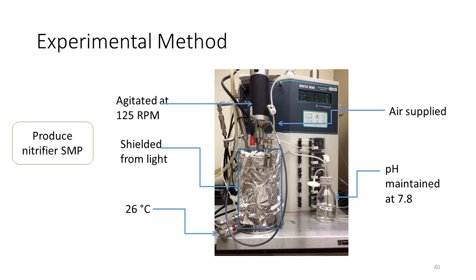And this was key because during ammonia oxidation, the pH goes down. However, the nitrifiers would die if the pH dropped below 6. So as the pH would continue to go down, the machine would continue to add carbonate. It actually served two purposes: it supplied them with more carbon source and it would raise the pH. So the nitrifiers in this system had unlimited electron acceptor, the oxygen, and they had unlimited carbon. So the only limiting substrate was ammonia, and the initial concentration of ammonia was 890 milligrams per liter, and I ran it until it was under 1 milligram per liter.